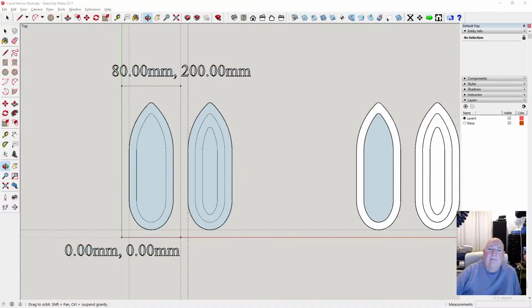Right, we're back. I've measured some wood. I've got some actually 20mm and 15mm, so we're going to end up with a bit more space than we thought. That's okay. Doesn't matter, the model can stay as it is as we affect the G code on here. Okay, so what we need to do now is just pocket out that bit there.